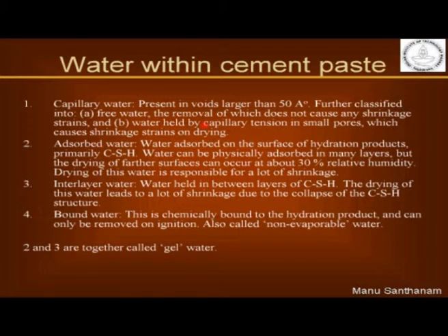So it's needless to add that when you have the gel pores and the gel pores have water inside them, it can obviously be a very high level of shrinkage that can be associated with that. Okay. So gel pore water is usually in two forms. You have adsorbed water or interlayer water.